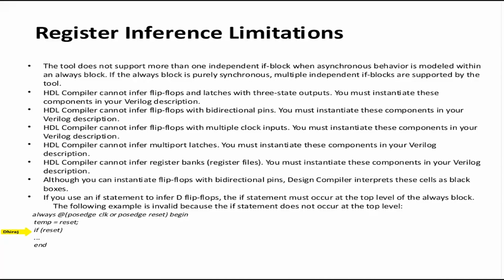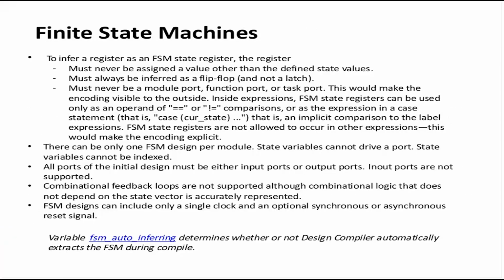So this tells you that you cannot arbitrarily code RTL. You have a set of guidelines which you should follow to make sure that Design Compiler draws the correct inference. We talk about finite state machines. Again, there is a set of rules about finite state machines. The state register must never be assigned a value other than the defined state values, and a finite state machine cannot have latches. It must always have flip-flops.